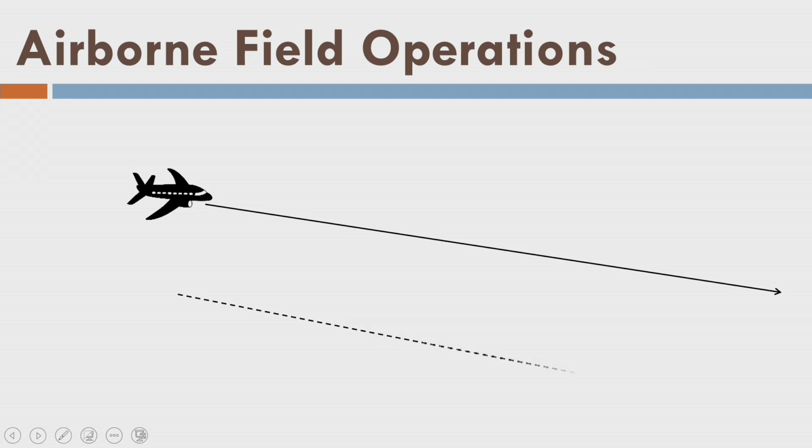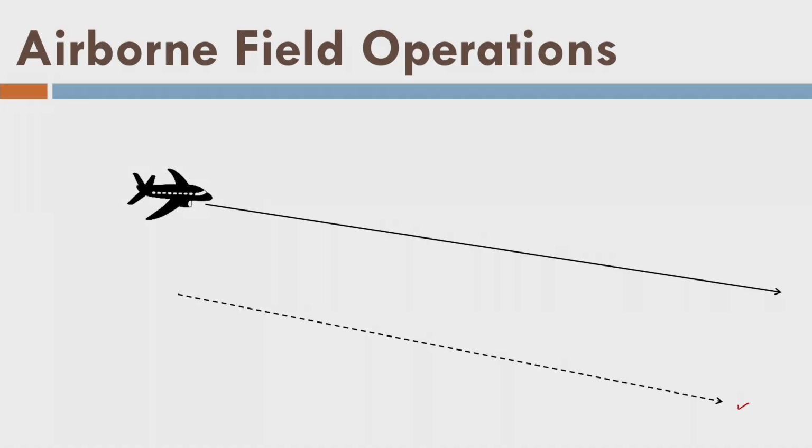Okay, so now we have understood the role of the DGPS and IMU. Now let us say that we have used the IMU and the DGPS, and we have found the trajectory of my aircraft. So this is the ideal trajectory, and this is the flight line on the ground surface. Fine. What will happen now? Because we know the trajectory points at each and every point within 1 second also. So now we can say that the laser scanner, when mounted on an aircraft, is acquiring data at each and every fraction of a second.